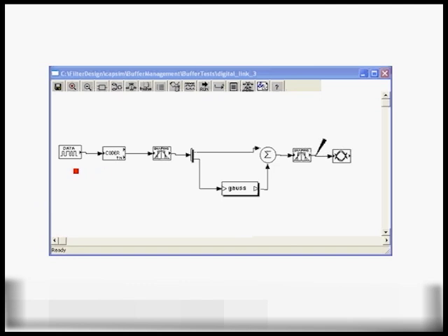So in this fashion, not all of the data is generated all at once. Only chunks of data are generated, and the source block keeps track of how much data it has generated. Once the specified number in the parameter has been generated, it stops generating data, and eventually the simulation runs into a deadlock where there are no more samples to be processed, consumed or generated, and the simulation stops. So this is very important to realize in the kernel simulation model and scheduling.